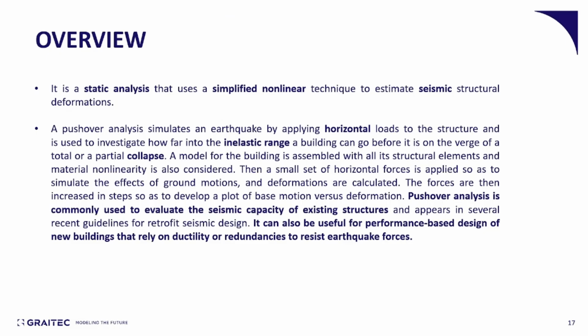The pushover analysis is a static analysis that uses a simplified nonlinear technique to estimate the seismic structural deformations of the structure. A pushover analysis simulates an earthquake by applying horizontal loads to the structure and is used to investigate how far into the inelastic range a building can go before it is on the verge of a total or partial collapse. A model for the building is assembled with all its structural elements, and material nonlinearity is also considered.